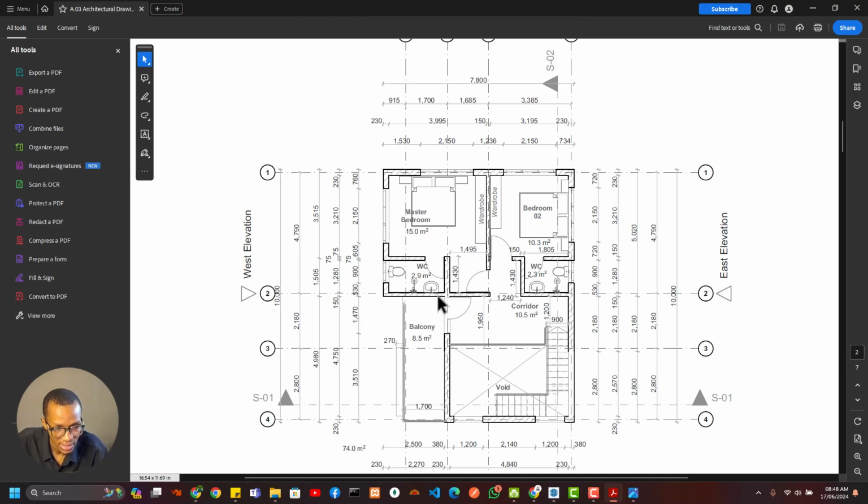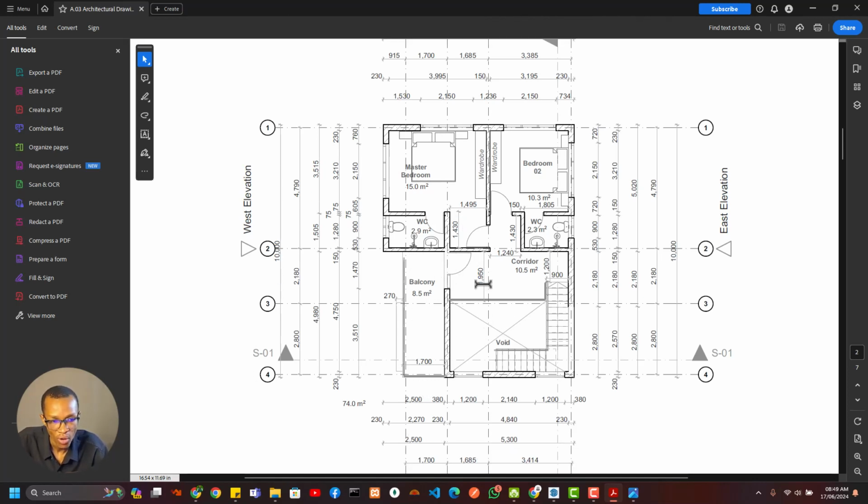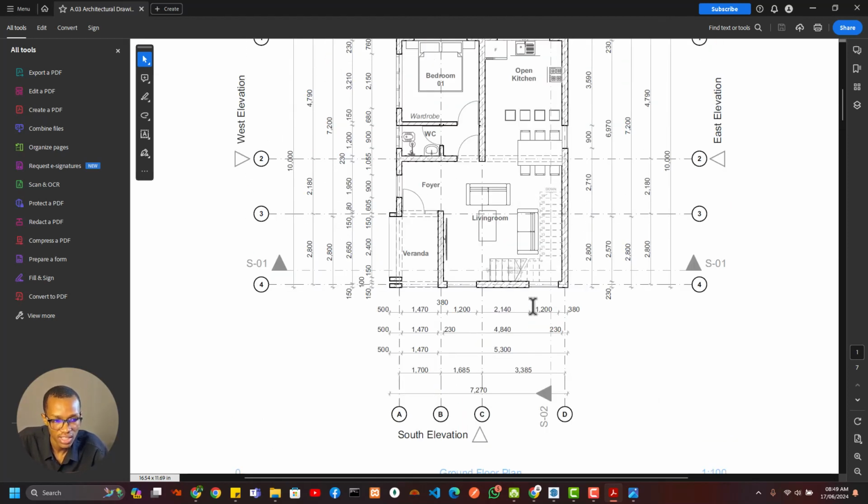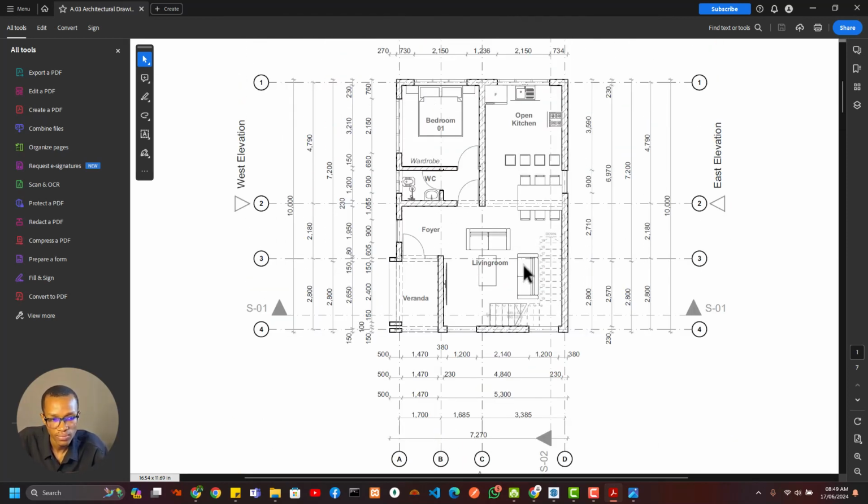What won't I see again? All right, I would see this wall because of going through like this on the first floor plan. All right, so sections are usually done on an elevation plane. So what that means is you see all the floor plans in alignment. So we see first floor, second floor, and whatever floor, even roof plan, you see all of them cut through.